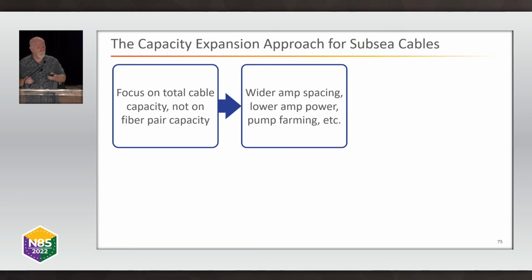do sharing of your backup pump lasers, because remember, these amplifiers in a submarine cable, they live under the ocean for 25 years. So if your amplifier pump lasers burn out, you can't lift the cable and replace the amplifier housing. That's very bad. That's very expensive. What you do, you put backup lasers in those housings. And normally it's 1-for-1 backups, which uses a lot more power. But if you can find ways to share backup pumps between all the different fiber pairs, you could economize on power.